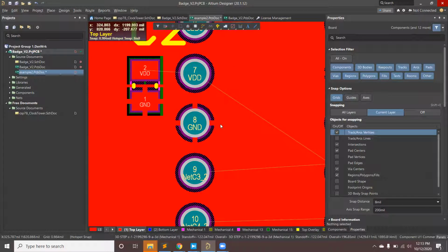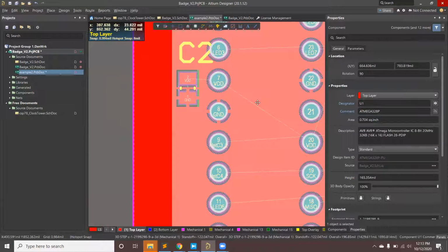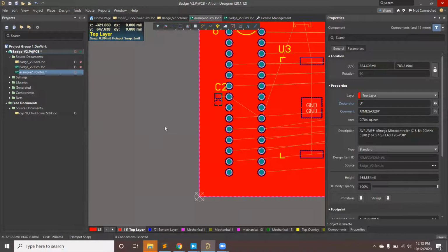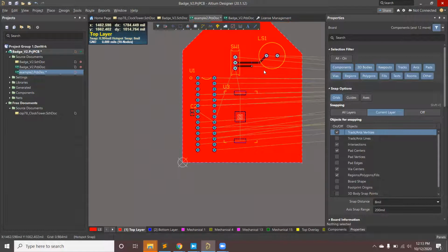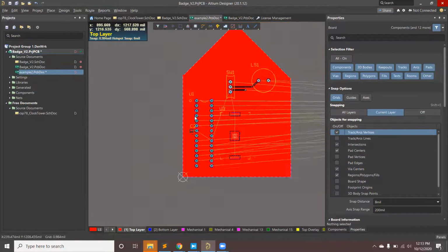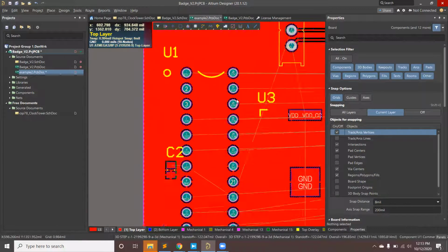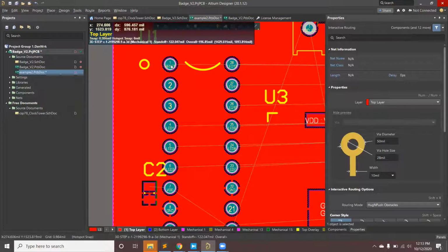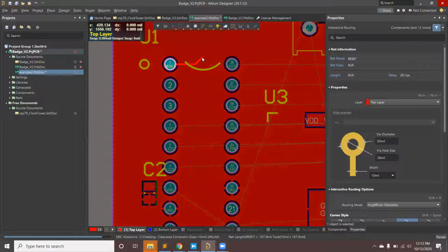So yeah, there'll just be this thermal relief in the sense that it's not going to be directly connected to the big plane. Either way, it's probably not going to matter. You're hand soldering this, so don't really worry about it. That's kind of what I was saying when I said it was pretty hard to look at this, and also if you pour this and then you try to make traces, it's going to cause problems.